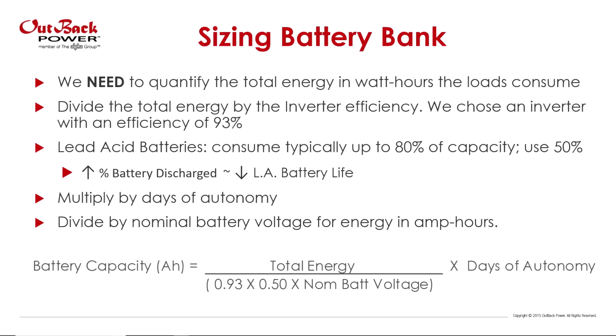Okay, so system designs with lead acid batteries typically only discharge the batteries around 50%. Normally, discharging lead acid batteries more than 80% is not recommended. You could discharge as much as you want, but there are trade-offs between percent discharge and battery life. Battery manufacturers provide literature on that trade-off, so designers can decide what percent they want to discharge the batteries for their application.